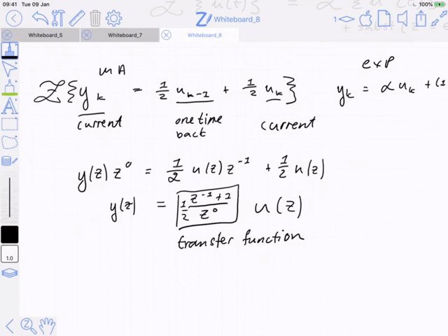Really, if I have a difference equation, the Z transform basically follows from inspection, if I have linear difference equations. And the good news is I will never expect you to do the Z transform of any nonlinear difference equations. Obviously you could go through similar steps like the whole linearization stuff, but all the ones that you're going to worry about right now will always be linear. The big ones that you really want to know about right now are the filters, right? So you want to know about these moving average filters, and you want to know about the exponential filter.